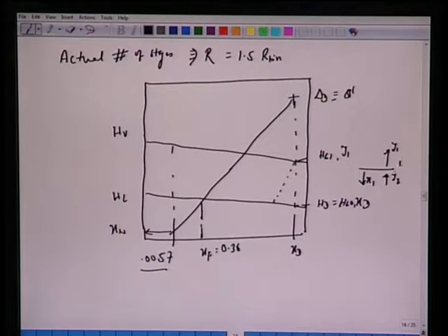So it's plate 1. So Y1, X1, if you connect with this, this is the first operating line, giving a relation between X1 and Y1, Y2. So we have this Y2, and again this is in equilibrium with the liquid which leaves here. If we connect this from Y2, again we have another equilibrium. So this stream is in equilibrium with this X2, so we get X2. We connect with this del point here to obtain this vapor, which is Y3.